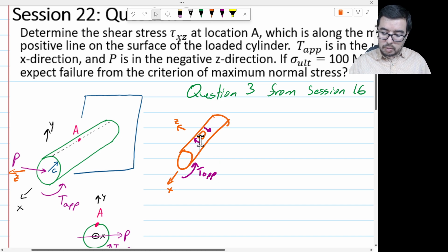As you may recall from our time together, we really only need one arrow on one of the sides to be able to draw all the shear stresses. So I don't even have to know that it's that direction. Once I have one, I know that I've got to have another pointing to that corner, and then I have these over here that are pointing to each other. That way, the element is in equilibrium with respect to the shear stresses that we're placing on it.